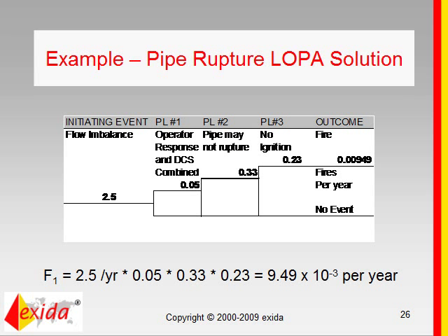The same actually is also true for 61511. If you go to part 3, keep in mind it's informative, there are some suggested protection layer probability of failures. There are some other industry books. I'm thinking of Loss Prevention by Lees, a 3-volume book or 4-volume book, I forgot, I think it's 3, which addresses these. And then we also have, for example, the CCPS guideline for safe automation of process industry with some sample information. And there are other data sources available.